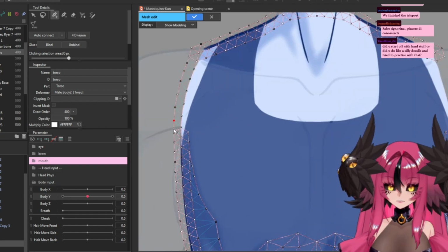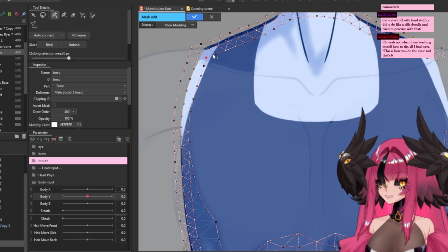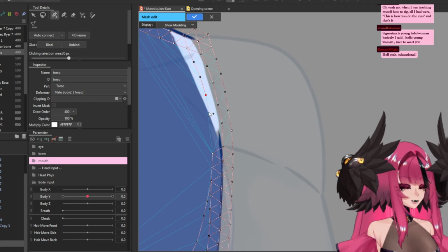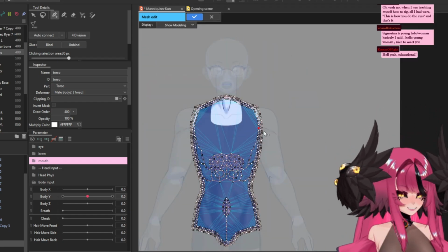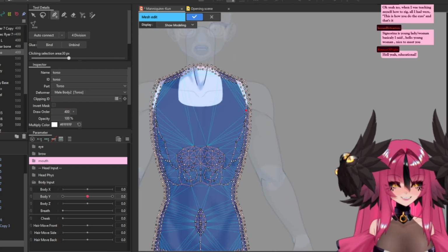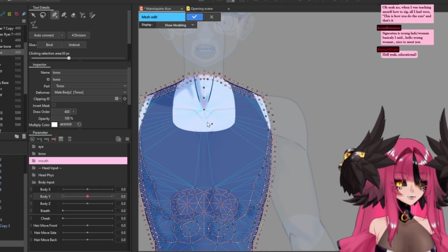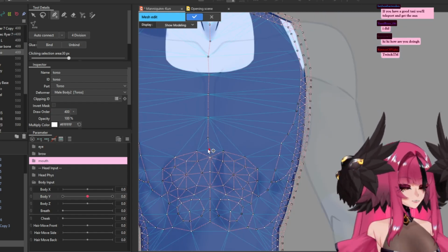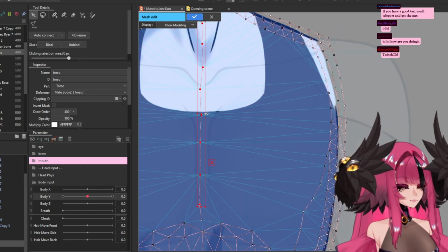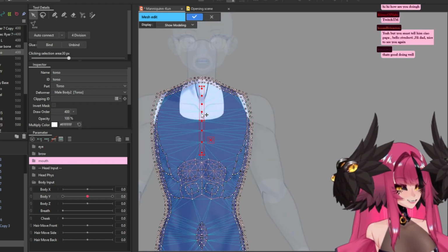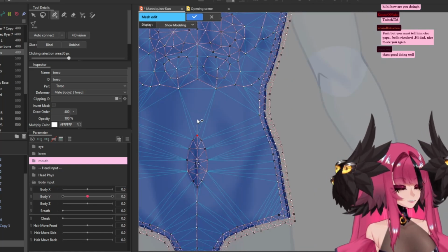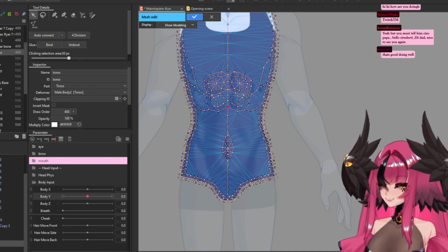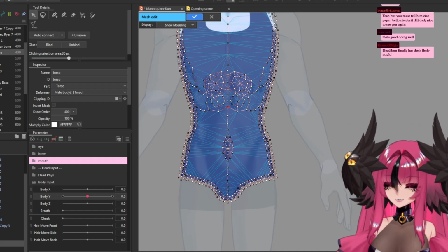Now that we have all of our verts merged together, it's just going through the mesh and cleaning things up and making sure all of the mesh is closed so that there are no open holes. If we have open holes, it will let you know when you try to exit. It will say incorrect mesh found. You just have to make sure you go around and get everything right. And of course, we're going to go around and make sure that we have all of the shadows or clear component lines sorted out and meshed so we can get some nice lines. Until then, enjoy the speed meshing and we'll move on to the next parts.